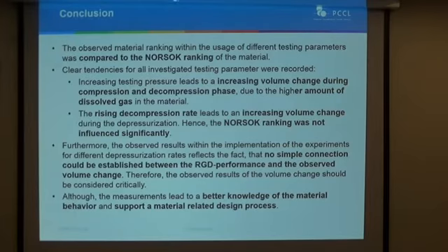To come to an end, we have seen a clear influence on the volume observed or measured during the compression and decompression phases, both for the rising decompression rate as well as for the increased amount of dissolved gas in the material due to the higher pressurization of the material. However, we have also seen that we have no clear connection to the NORSOK material ranking in terms of the higher decompression rate, and therefore we cannot easily correlate both material characterization techniques.